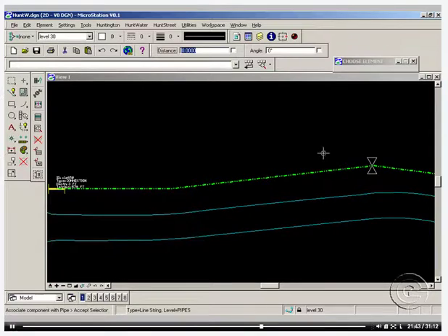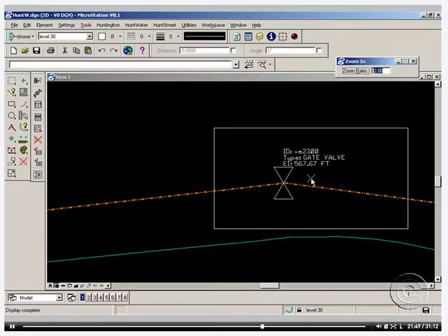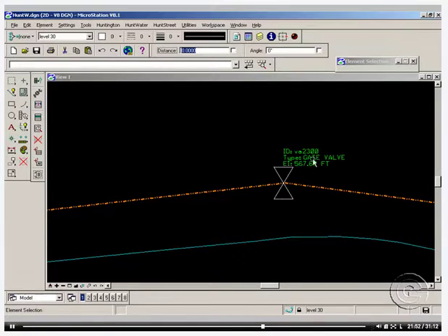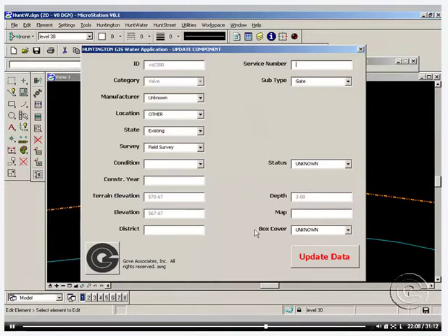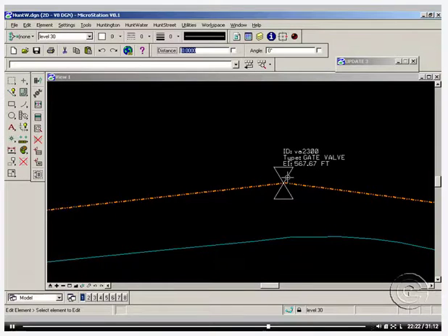We go ahead and click on that pipe, accept it, and as you can see here, our valve is now in the database, connected to that pipe, and showing the information that we just put in that form, the ID of the valve, the type of valve it is, gate, and calculating also the elevation of that component, giving the elevation that we have on the pipe, and so on. And we could again just go in here using the review attribute data and tag onto that valve, accept it, and as you can see, now we have basically a component on that graphic that before did not have any attributes and now has attributes and is connected to a certain pipe. Just go ahead and click it here and exit that form.